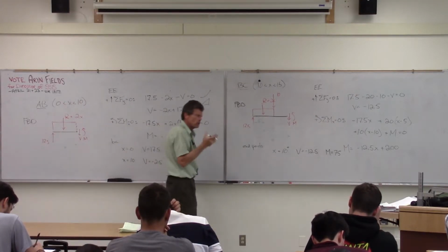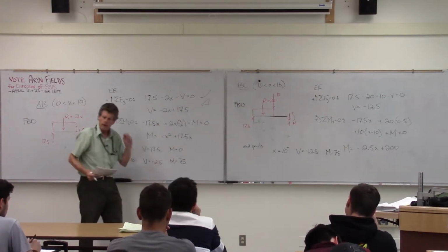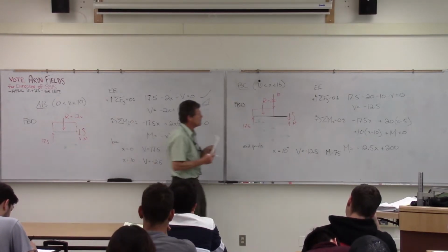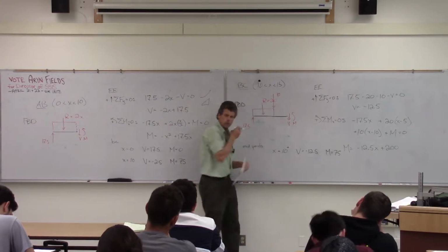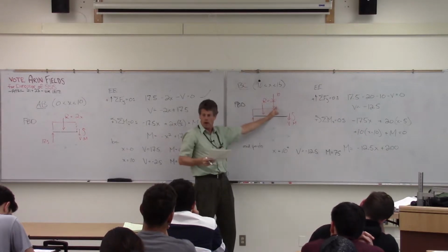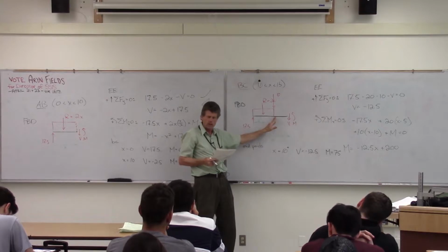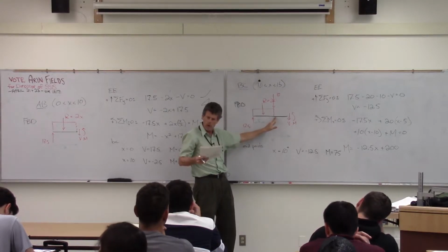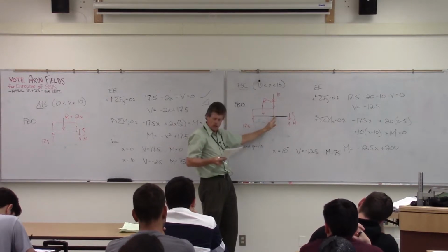But it also helps us when we're drawing this because let's go to the moment diagram. It's 75 here and 75 here. Well, let's think about it in terms of a concentrated load as I go across this point there of that 10. Yeah, the 10 kip load shows up, but I have virtually no moment arm there, right? So I shouldn't expect to see any sort of jump in my moment diagram due to a concentrated load because it starts off small.